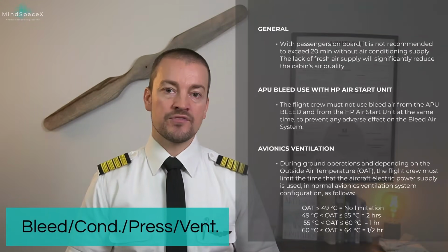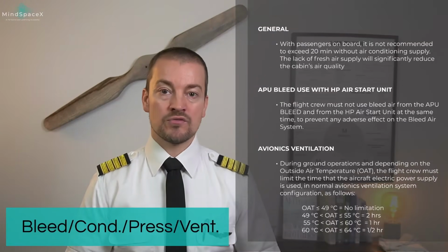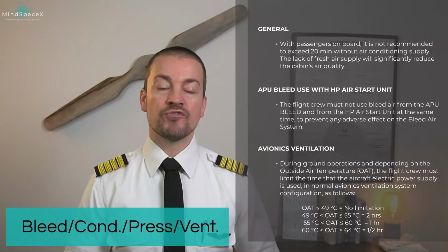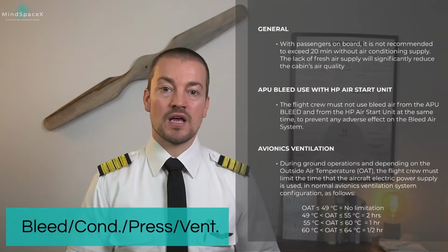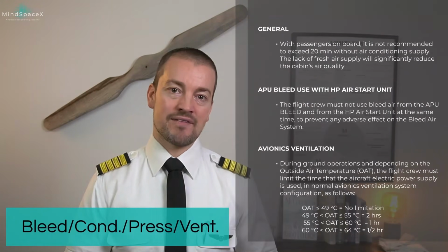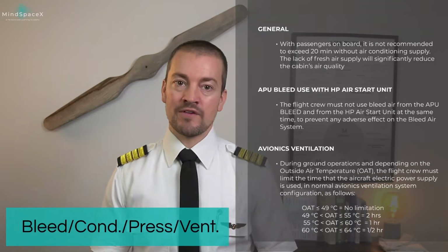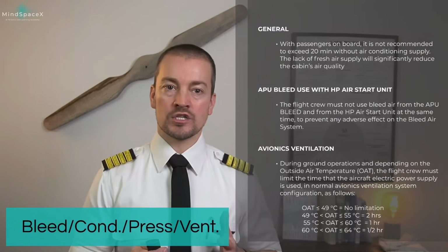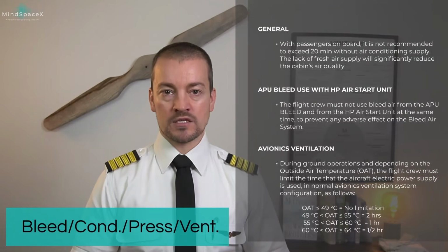Between 49 and 55, it's 2 hours maximum use. 55 to 60 degrees Celsius, 1 hour use. And from 60 degrees to 64 degrees Celsius, which is also the maximum operating temperature for the aircraft outside, that is half an hour. Having hot air like this blowing over the avionics is not going to cool effectively the avionics and could cause damage to all the components within this avionics bay.